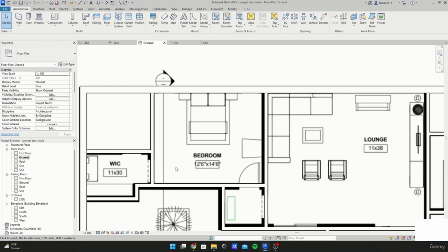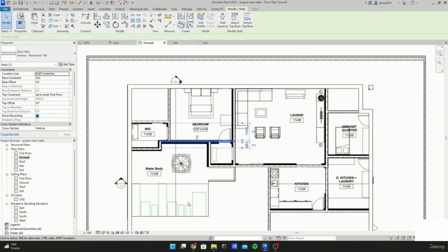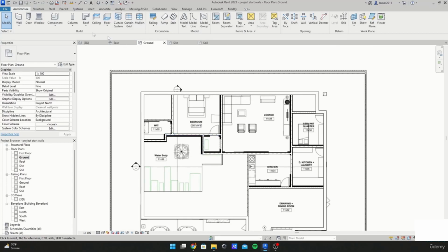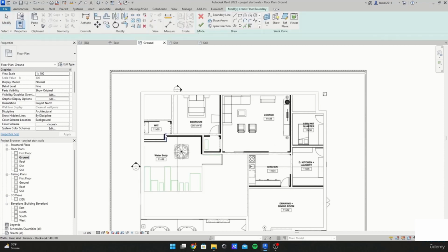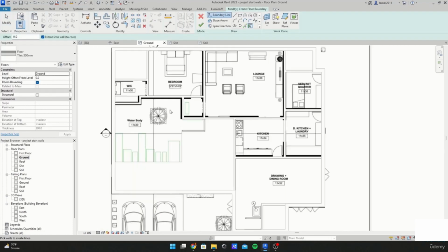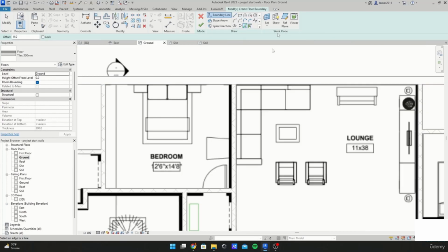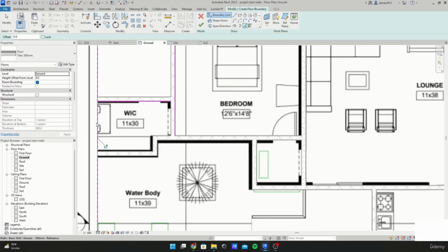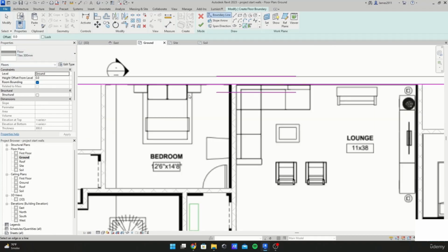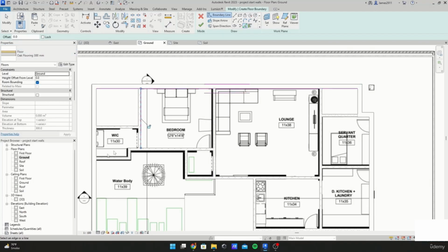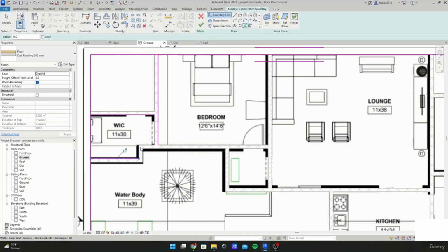So, moving on. We're now just going to go through all the floors. I'll go into floors again. I'll just select all the floors. I'll draw out all my walls. I'll click over here and over here. Just select all the remaining walls that floors. Sorry, we don't have this strip. Rather, we have the oak flooring. Just click and select all of the walls surrounding the rooms you want to change.